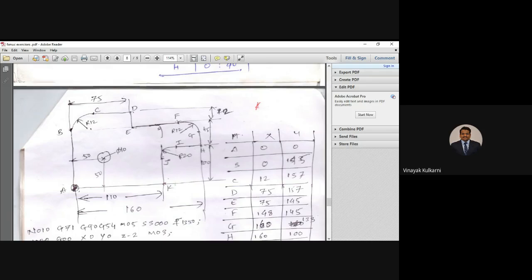Now since I am moving downwards, I don't have x value, means I don't have I value. So I am moving downwards, that is negative y axis. It will be G02 X160 Y133 J minus 12, I0 J minus 12 and R12. I0 J minus 12, because from here I am moving 12 distance downwards, that is negative y axis, imaginary axis to be called as J, my J minus 12, I0 and finish it off. So my cutting will take place till here. Then again moving from here, coming here.